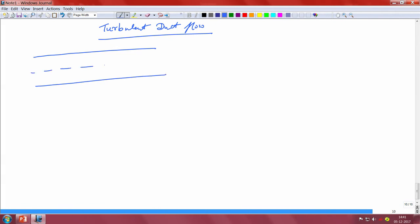You consider this as your duct. So, this is your R, this is your X, this is U bar, this is your V bar. I am not going to redraw it once again. This is what we are going to carry forward in the next class also. So, again we are trying to do the same thing like Prandtl's approach. That means we are doing the Reynolds averaged Navier-Stokes equation. So, for this particular duct, the equations are